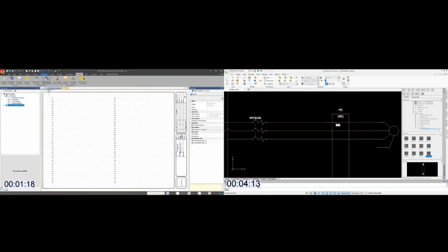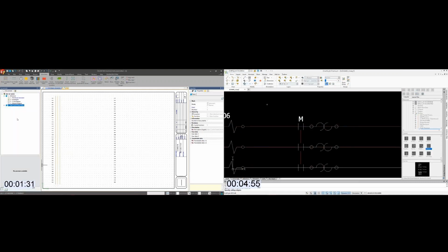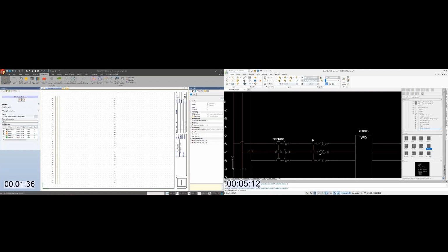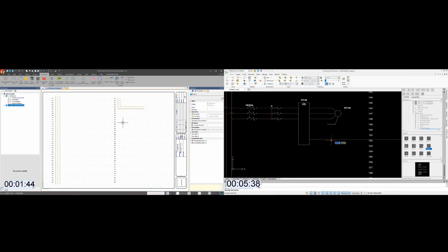Now over here on the left on SolidWorks Electrical, I'm a minute and a half in, and I'm starting to create some drawings. So here I'm going to put in intelligent wires. As you can see, I already have defined the correct wire style for each of these wires. I don't have to define that after the fact. These are fully intelligent with the physical properties of this wire, such as gauge, etc. So I'm coming over. This time I only pulled 2 phases to complete the circuit, as you would see. And so again, I've already started creating a fully intelligent drawing, populated the title block, added some intelligent wires, and starting to build that circuit. Again, all using intelligent tools such as insert wire.